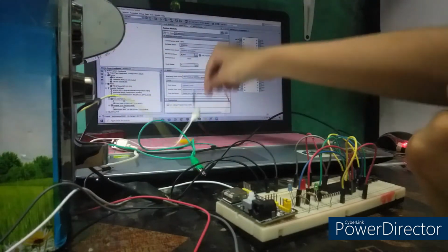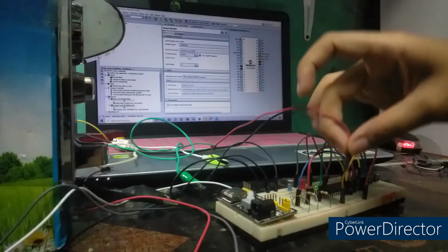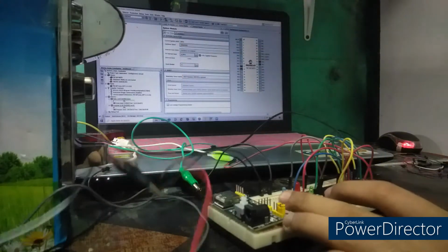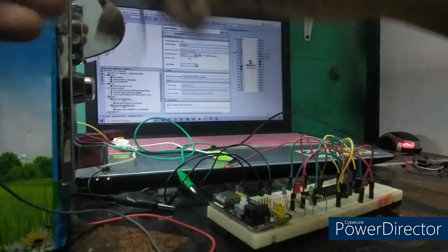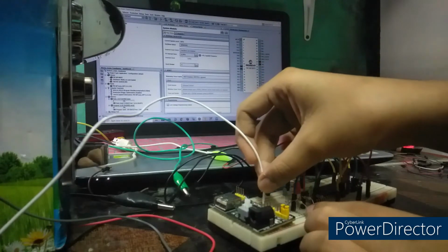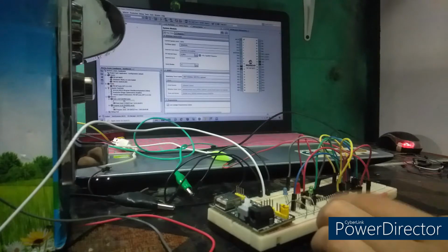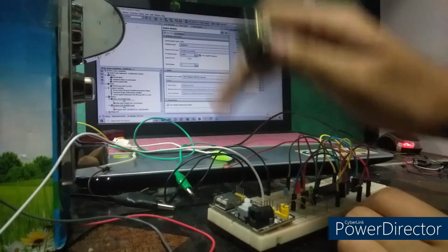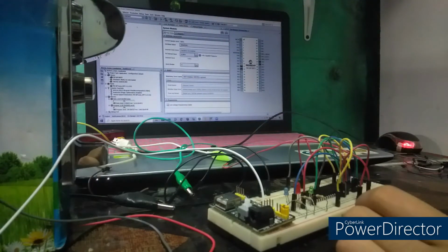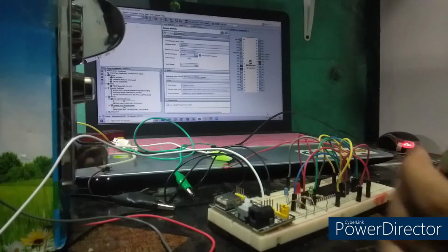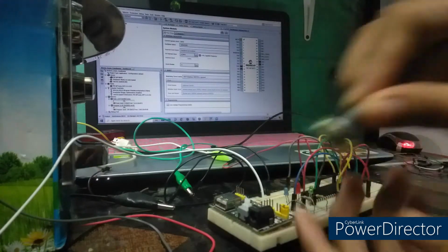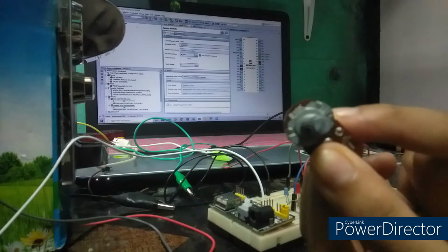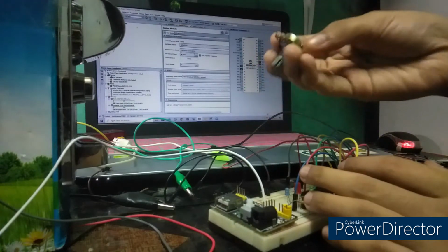And then let's connect the positive terminal of our 5 volts. And then we will be connecting the counter, or the white wire, from our coin acceptor. This will serve as our digital input that will be performing the function of the timer 0, which is connected to the RA4. Since we will not be directly connecting the white wire of the coin acceptor to the IC, because it may result in a malfunction of our IC, we will be using a potentiometer as our pull-up resistor. This is 10 kilo ohm. So from 0, I'll just adjust it to its maximum rating, so it will give me a 10 kilo ohm resistance.